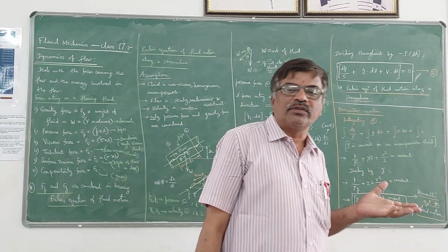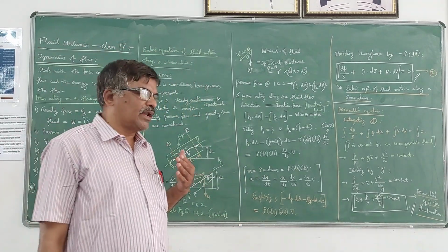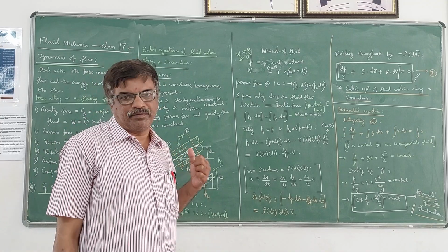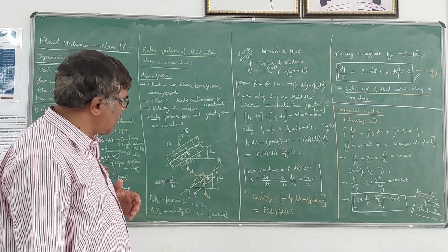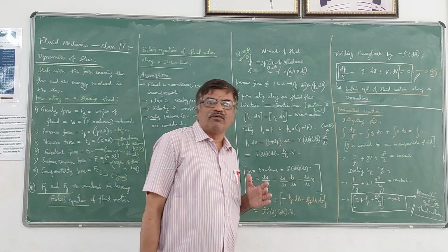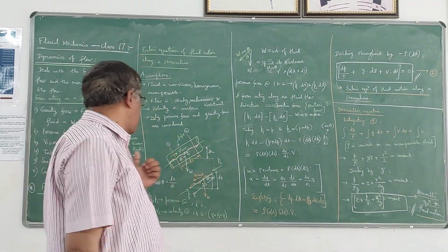They are based on another fundamental principle of mechanics, that is law of conservation of energy. Just like continuity equation was derived from law of conservation of mass, Euler's equation, Bernoulli's equation, they are derived using the law of conservation of energy. Of course, the basis for that is Newton's second law.